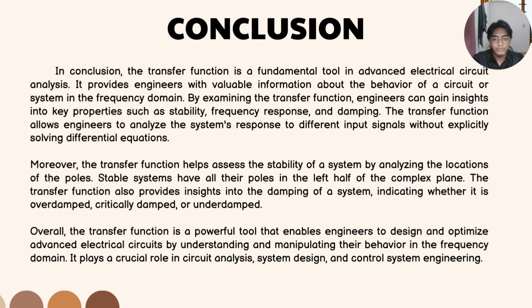Moreover, the transfer function helps assess the stability of a system by analyzing the location of the poles. Stable systems have all their poles in the left half of the complex plane. The transfer function also provides insight into the damping of a system, indicating whether it is overdamped, critically damped, or underdamped.